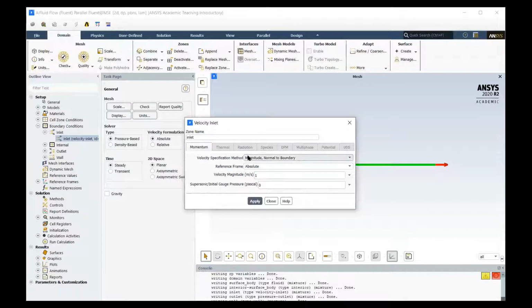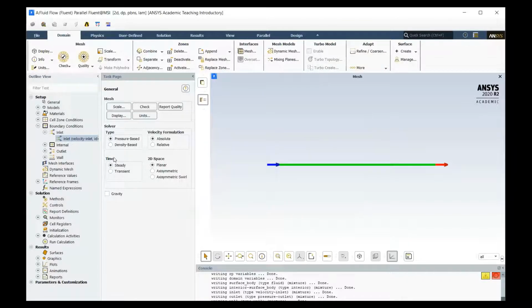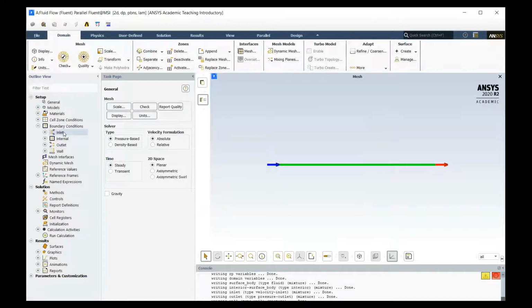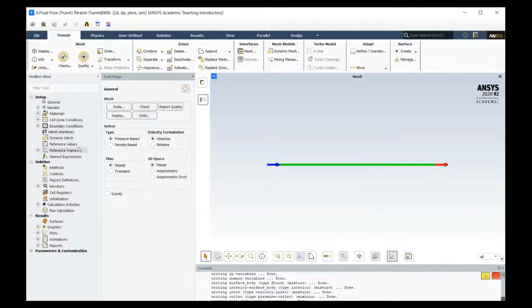And then this should be all that we need to allow the viscosity to be at 1000 to produce a nice laminar flow. For the boundary conditions, this is the only thing you need to change. Usually you can leave the outlet alone. I've never had to change the conditions for the outlet, just the inlet is all we need. Okay, so now we have changed the air, we have the right model, and our boundary conditions are set.